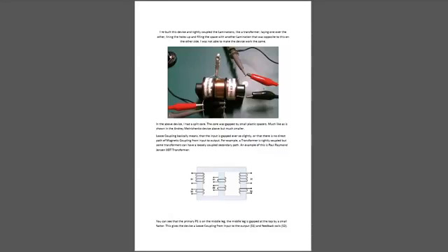For example, a transformer is tightly coupled but some transformers can have a loosely coupled secondary path. An example of this is Paul Raymond Jensen's UDT transformer. You can see that the primary P1 is on the middle leg, and the middle leg is gapped at the top by a small factor. This gives the device a loose coupling from input to the output, S1, and feedback coils, S2.